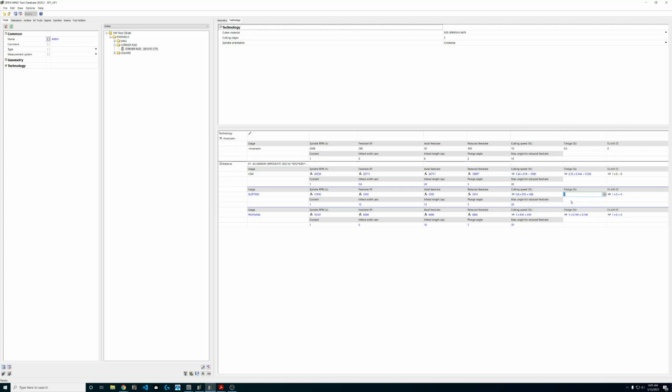And for the feed on the 12 millimeter tool, they just want to see 140. Oh, look at that. Wouldn't you believe it? They're confident that you can take the same chip load, whether you're in a full slotting situation or profiling, so long as you meet it with good surface footage. All right, we're going to save because we always save. Now we have the beginnings of a tool.